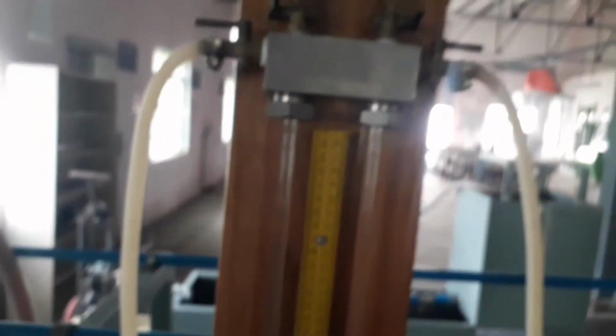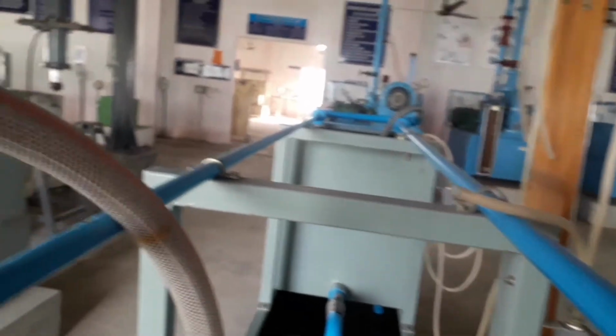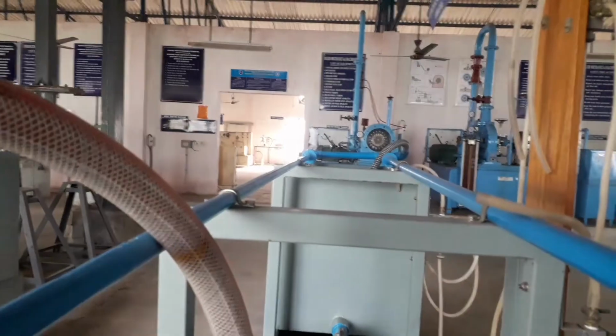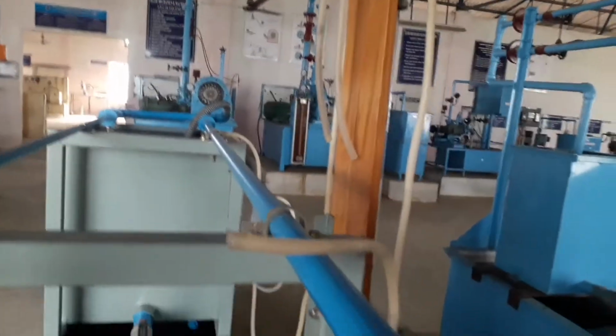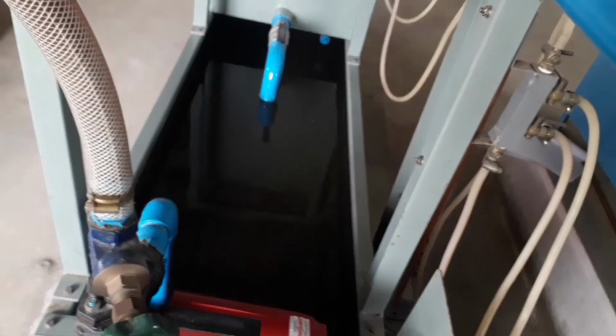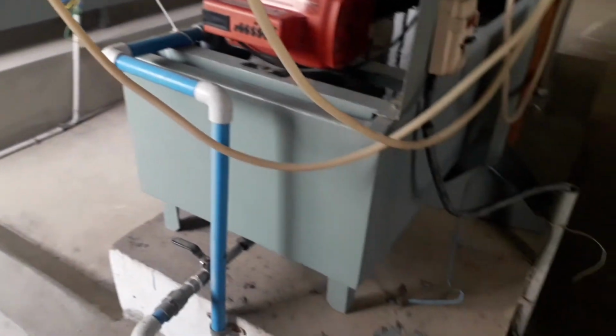Now, what is the main objective of this experiment? It is to determine the friction in pipes. What apparatus is required? Pipes having different diameters connected to a differential manometer, a collecting tank, a stopwatch, and a scale. These are the very important apparatus for this experiment. The pipe diameters, as already told, are two different sizes: 25 mm and 20 mm.